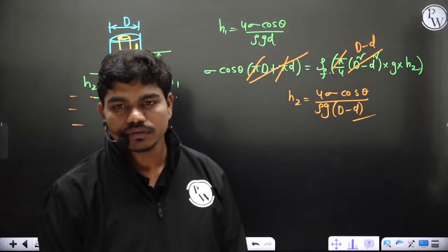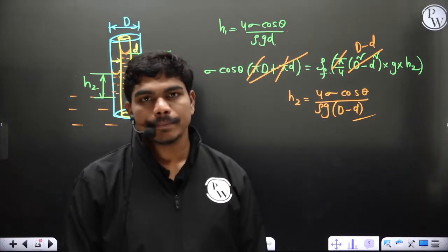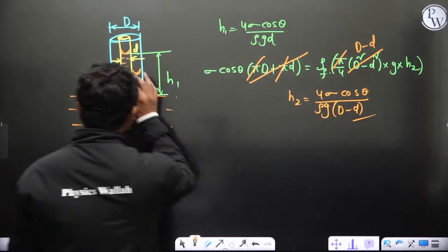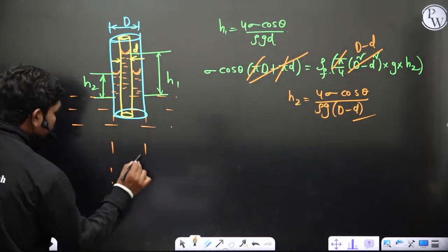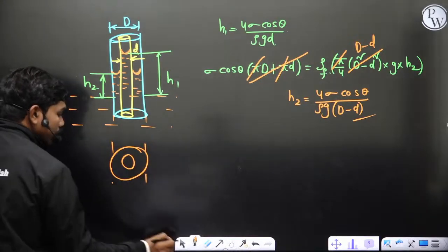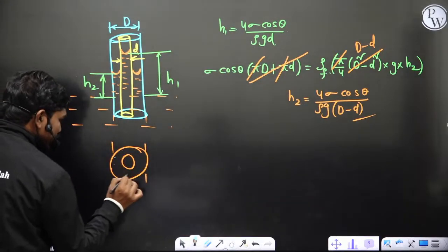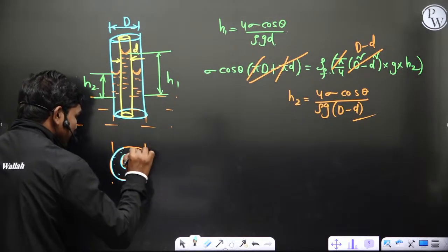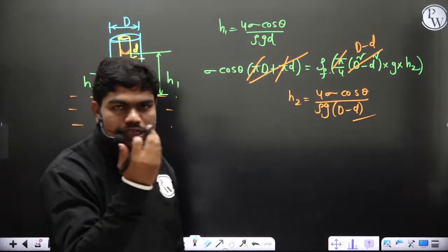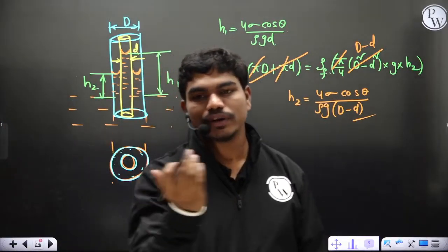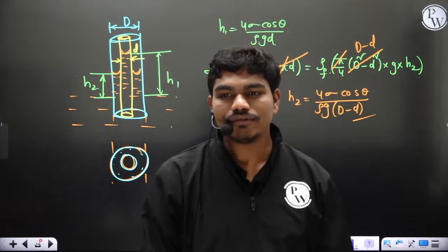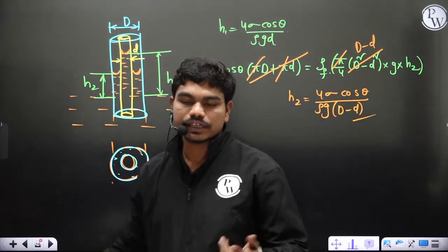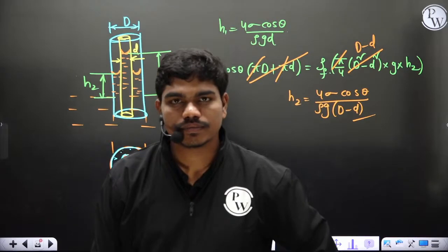Okay, so clear to all of you? Can you explain pi d plus pi D? Yeah, because whenever you see the top view, for example, the fluid which is in this location will make contact along this and also along this inner surface, correct? Along the outer surface of the inner tube and also the inner surface of the outer tube, the fluid makes contact. So there are two interfaces where you have fluid-solid contact. So obviously surface tension will act at these two interfaces. Clear?